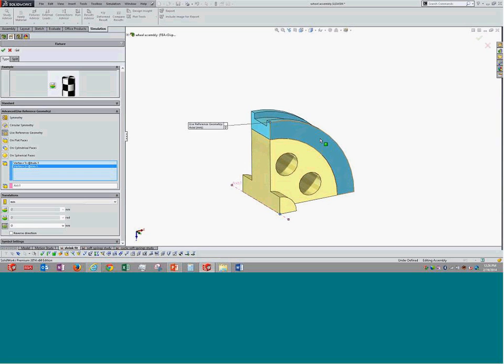Now, in the radial direction and circumferential direction there could be resistance, circumferential because of the symmetry condition, and radial because of the shrink fit. However, in the axial direction, that is the y direction, there is no restraint and the part can fly off. In such cases, we can use a restraint just to stabilize the model. So this is one way of doing it.